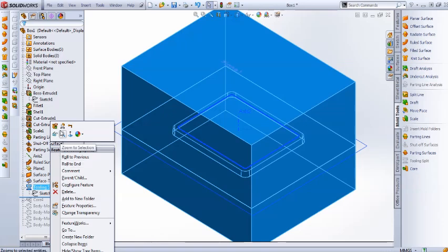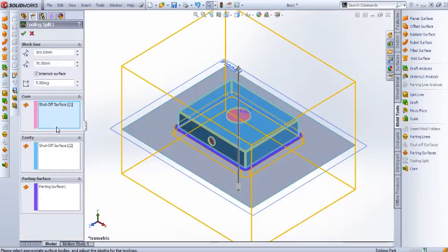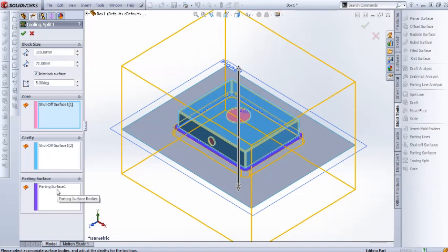The tooling split, you see, select the tooling split. Once the tooling split is selected, it will create the automatic dimension of the core side and cavity side. Check the interlock surface and give 5 degrees, and set up surface taken as core, and set up surface 1 of 2 is taken as cavity, and parting surface as parting surface. Now click OK.